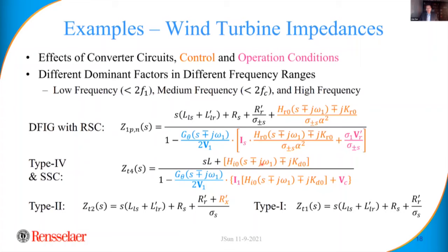That provides damping. And the integral gain in this form appears as a capacitor in the impedance, okay? So you get an inductor from the filter, you get a capacitor due to the integral gain of the current compensator, and you get the damping due to the resistance, okay? So it's a perfect RLC circuit.